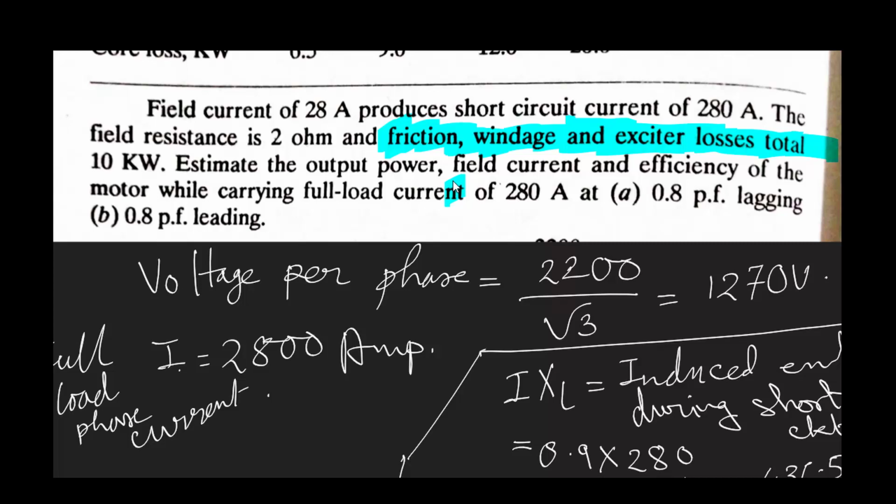Why? Because when you load your machine, it will draw more current, and drawing more current will result in more loss across your series branch. Typically from V to E, there will be more loss in your stator winding.